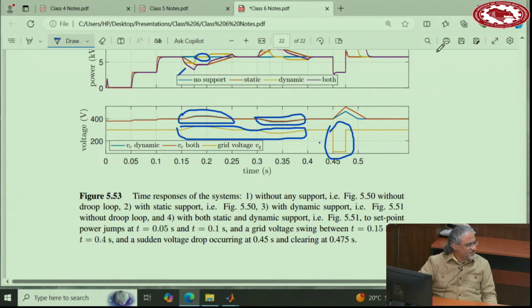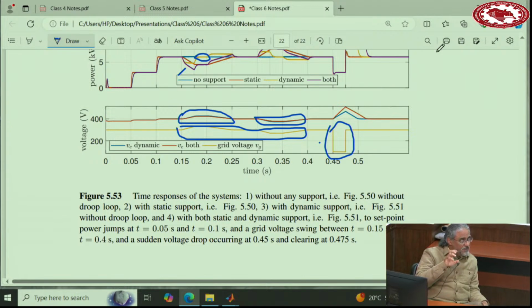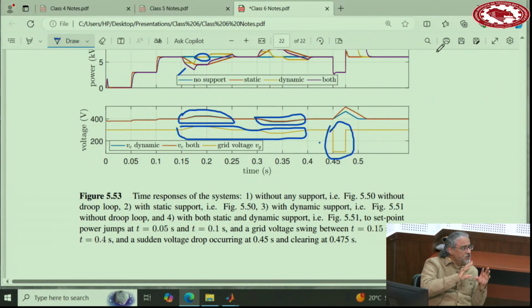Do these terms, this R1, J, impact the stability of our system and how we design these? In the full state feedback design, no, because we consider them in the design. Now if you designed partially the current controller and now start playing with R1 and J arbitrarily, yeah, you may destabilize the system. But if you choose them first, R1 and J, then go and design the entire system with full state feedback, you are guaranteed that it's stable.